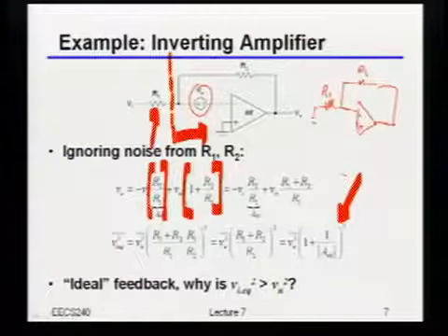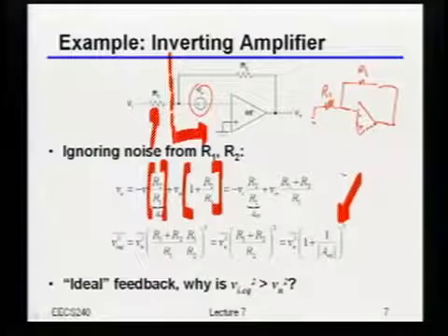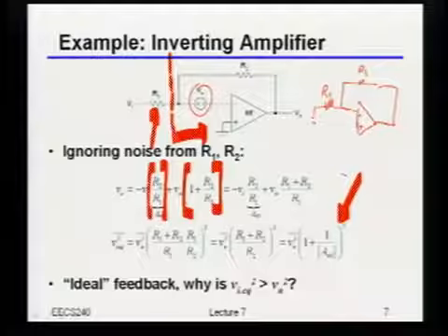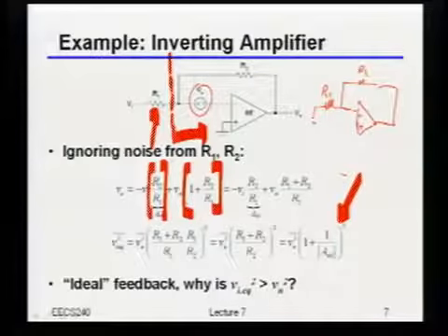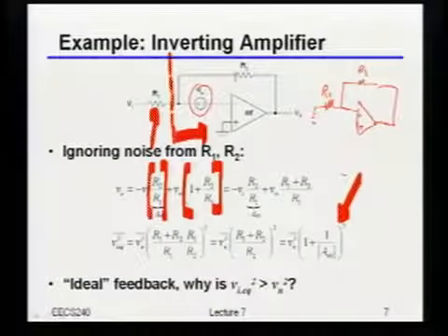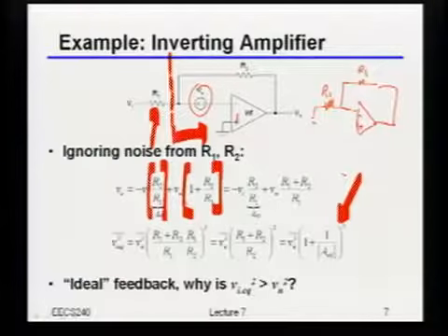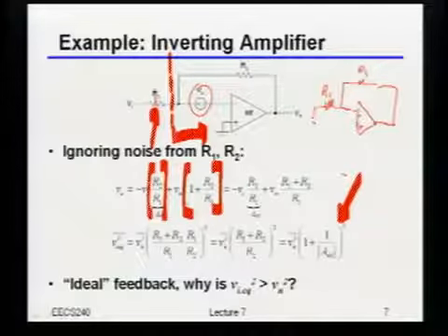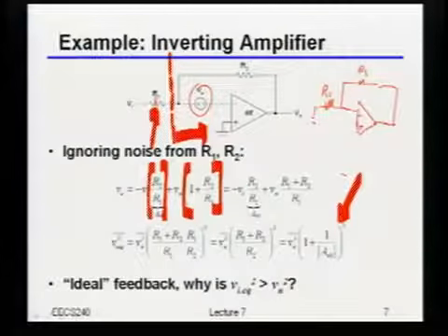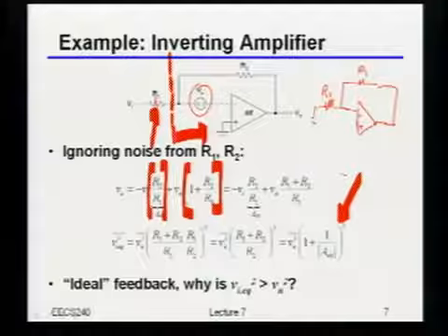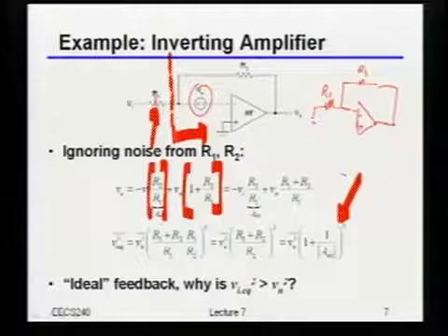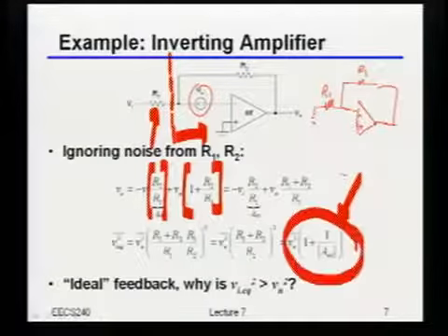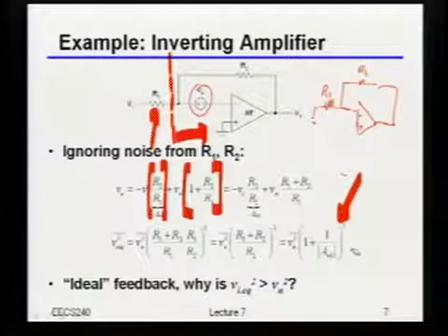So actually, maybe what you were saying before really is correct. I really did use the wrong topology, in the sense that I created a topology that has a certain input impedance, and then when I added this resistor over here, I basically messed up the optimum source impedance to drive it with, right? And by messing it up like that, that's what's responsible for that extra noise factor, okay?